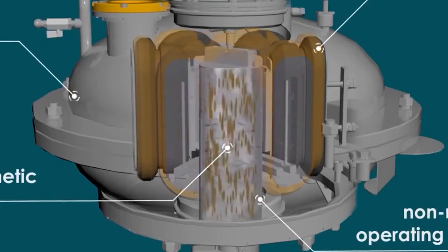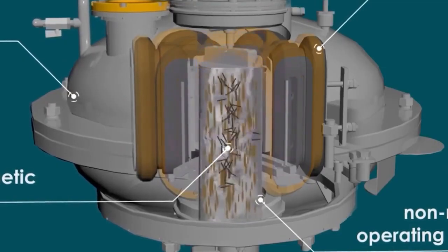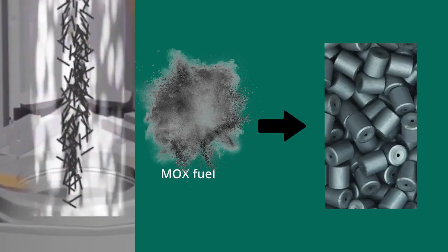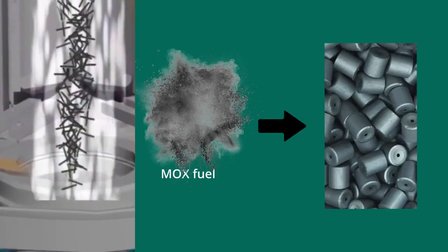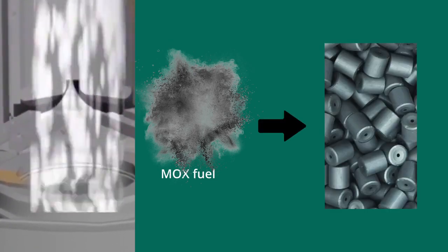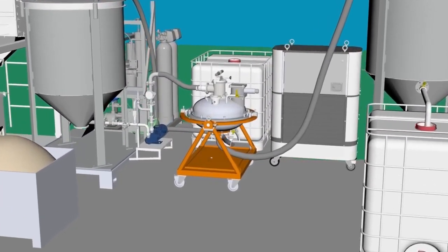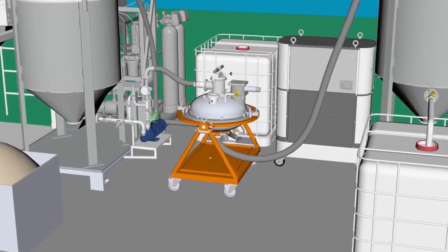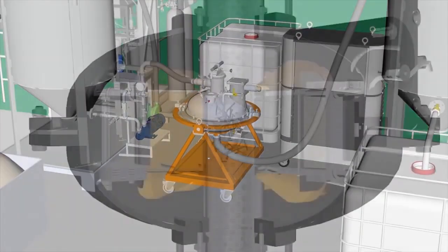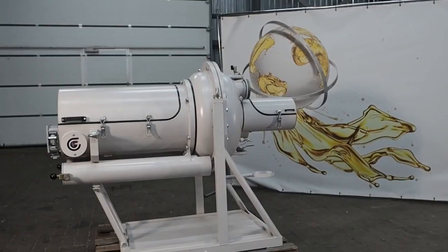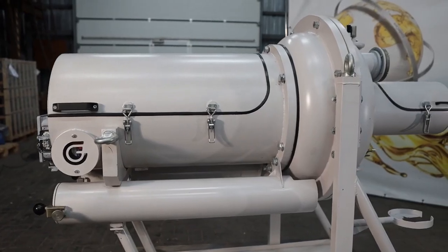Magnetostriction of ferromagnetic particles, etc. The comprehensive effect of the above-listed factors ensures rapid dispersion and homogenization of initial powders, which means achieving the high-quality molding powder of MOX-fuel for production of fuel rod pellets. Given the occupational hazard to operating personnel, automatic mode is used for feeding of initial constituents and ferromagnetic particles, as well as for cooling and discharge of finished molding powder.